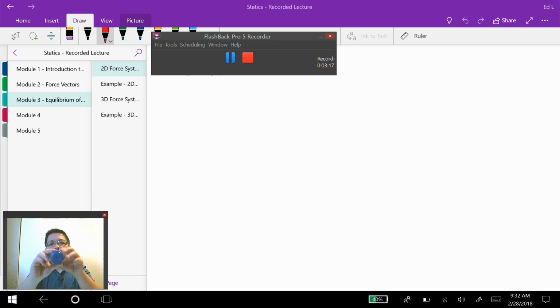Okay, so basically the equilibrium equation that we are going to set up here is to restrict the motion of the particle such that any forces acting on the particle will not cause this particle to move, or even if it moves, it has to move with a constant velocity. Why? Because constant velocity will not exert any acceleration, as you have learned in physics, and since it doesn't exert any acceleration, it will not exert any additional forces to the system. Okay, all right, so let's get started by setting this up for a two-dimensional system.